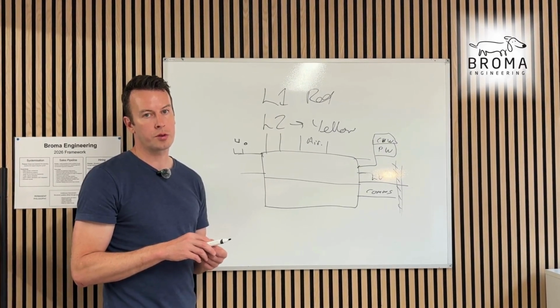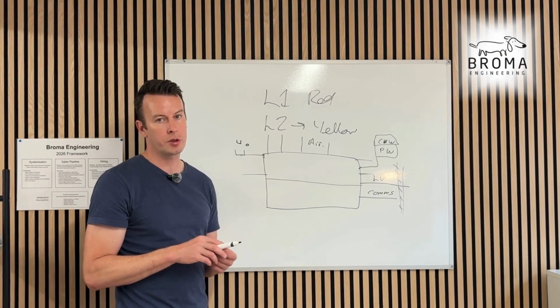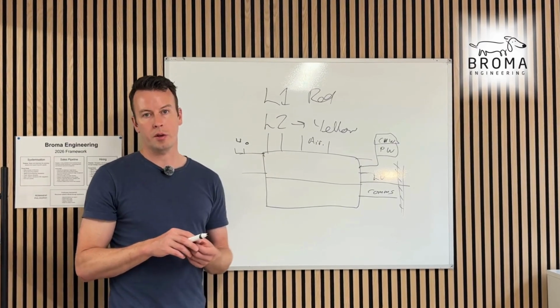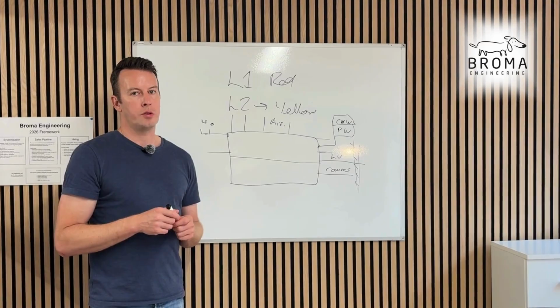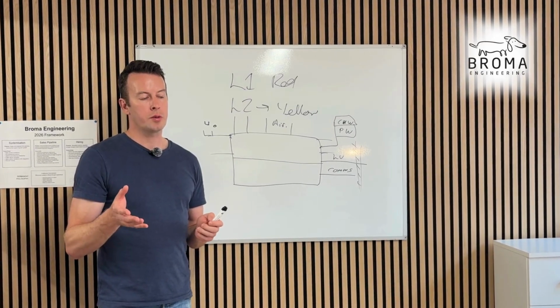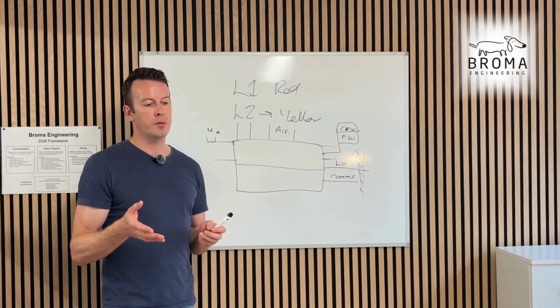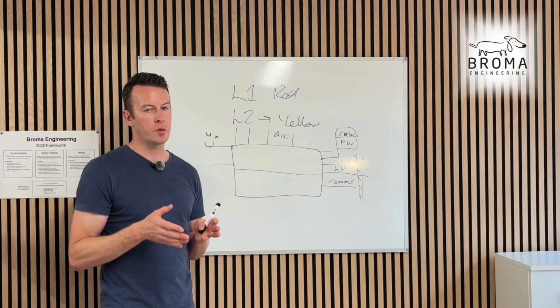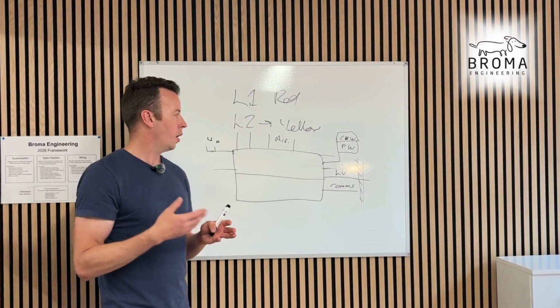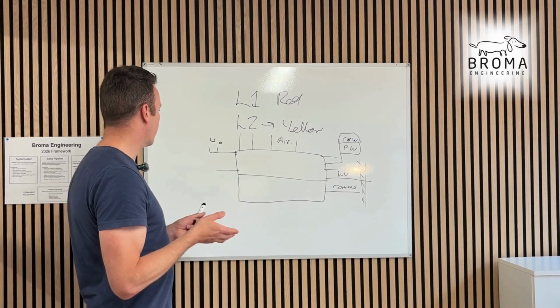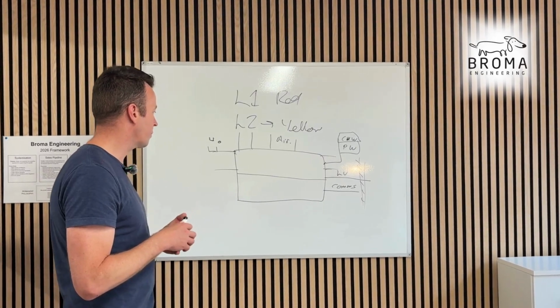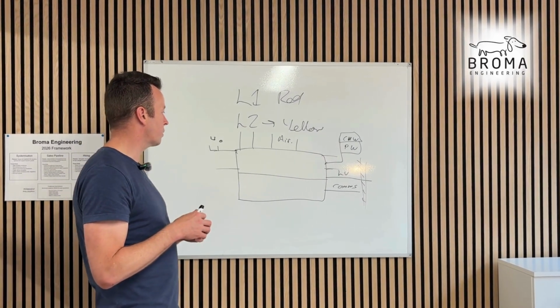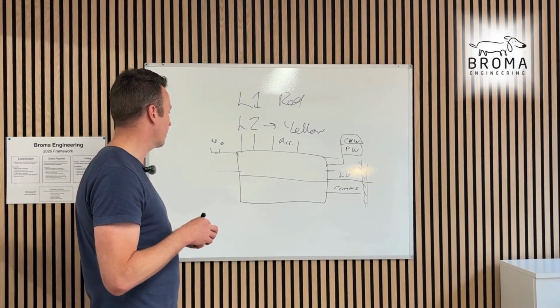So the roll-in routes in a perfect world will be mapped out in 3D, and you'll know exactly what's going to clash and what's not going to clash. So you're going to have to do planning sessions and brainstorming sessions with the teams and just focus on AHUs and see what sequence we are going to put stuff in. And then you're going to connect to your LV, make sure it's the right cables, you've technical submittals approved for the cables and the containment.